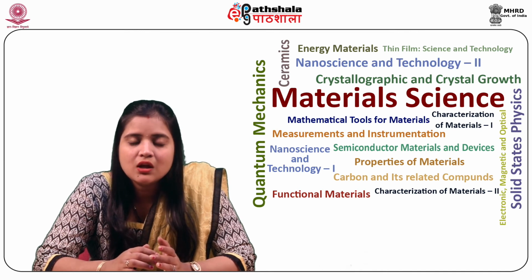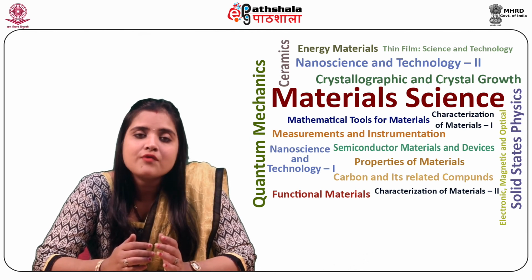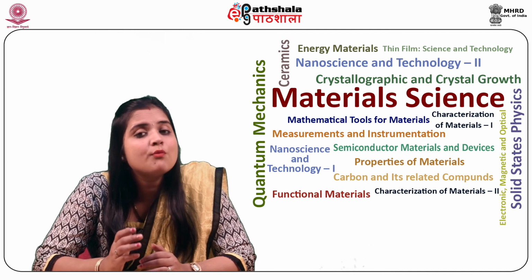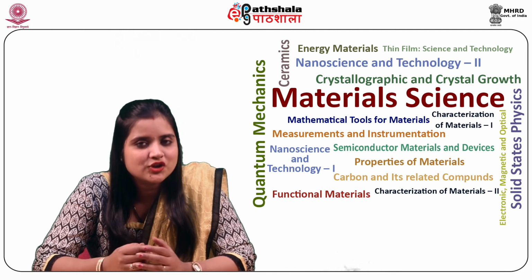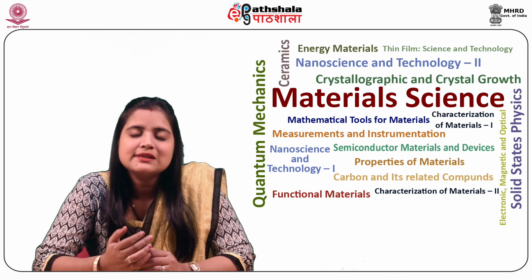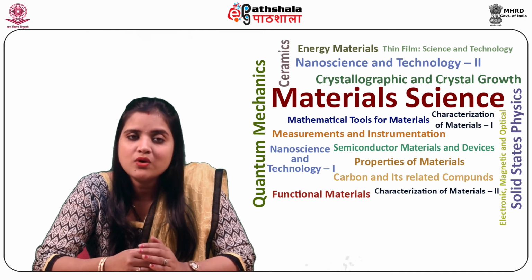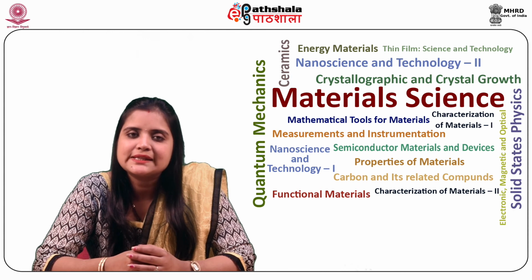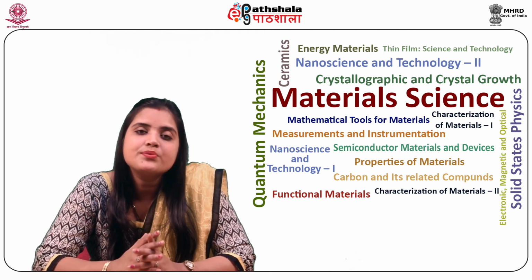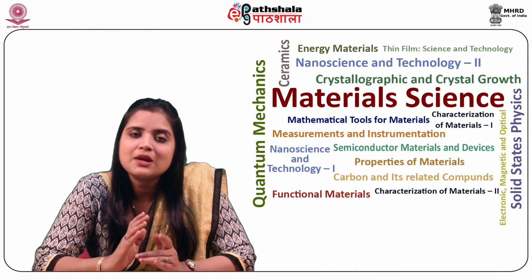In such a situation, it is customary to represent the dielectric data in terms of epsilon prime of omega and AC conductivity sigma AC in low mobility, or I can say insulating materials. The AC conductivity sigma AC can be expressed as sigma AC is equal to capital A into omega raised to power S, where capital A and S are the parameters. Such a frequency dependence in AC conductivity is observed in a wide variety of low mobility, amorphous, and crystalline materials,